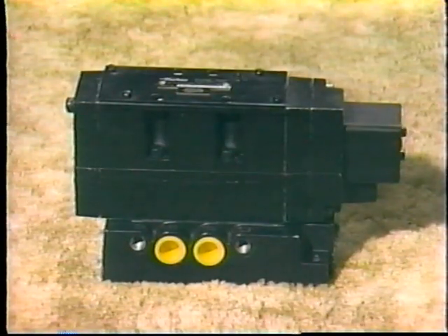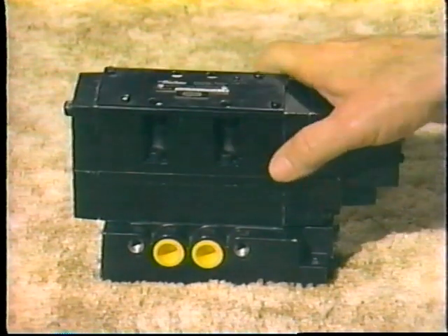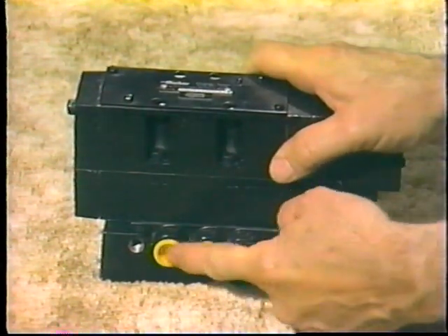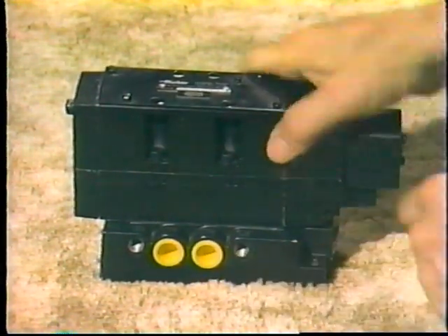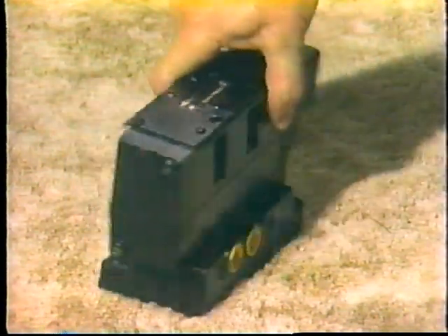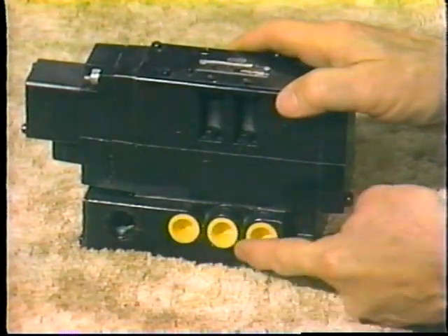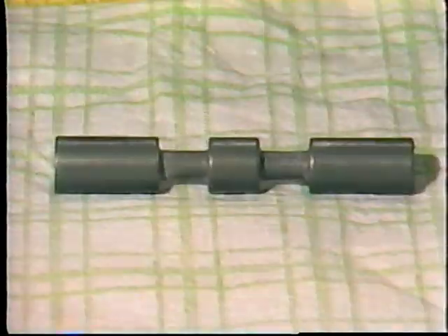Here is what a typical directional control valve looks like. There are openings or ports in the valve body. These allow connection to the ports of an actuator, like a double-acting cylinder, and to the air supply and exhaust. Now right here, I'd better mention that different manufacturers use different letters and numbers to identify these ports. You should check their literature before making an installation.